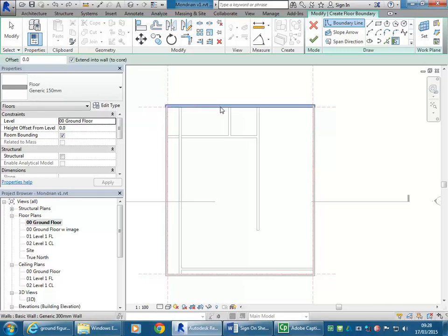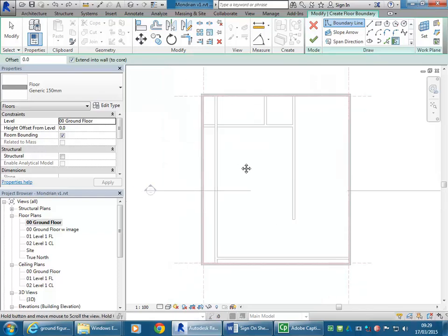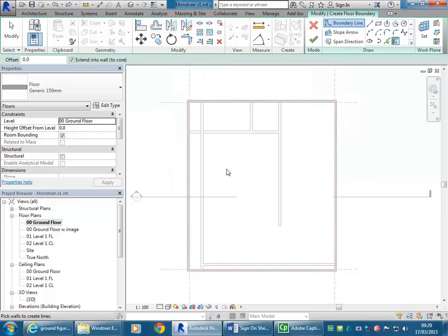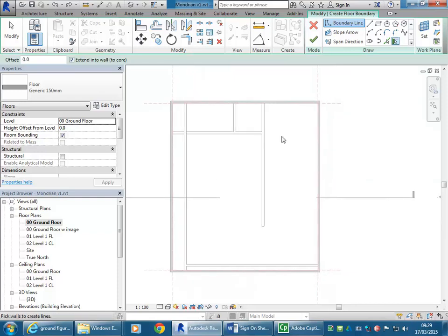Here it's letting me choose the wall, but that's to create part of my floor. And so I can only work with my floor sketch until I either cancel with the cross or tick to complete my floor. And it makes life easier because it means you just need to then focus on drawing the 2D shape that you want your floor to follow.